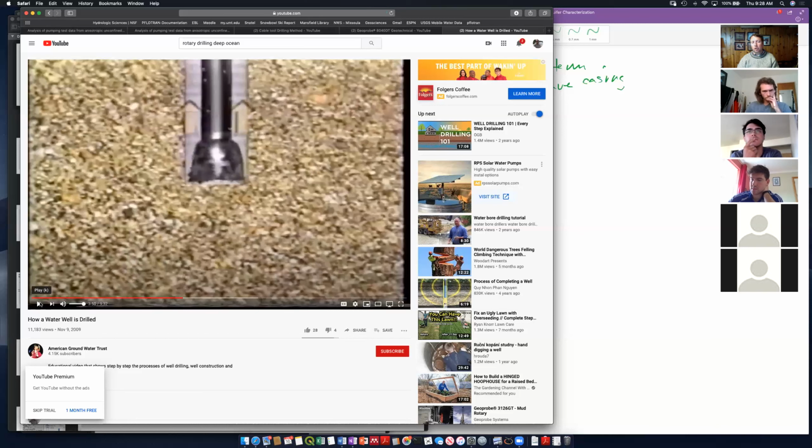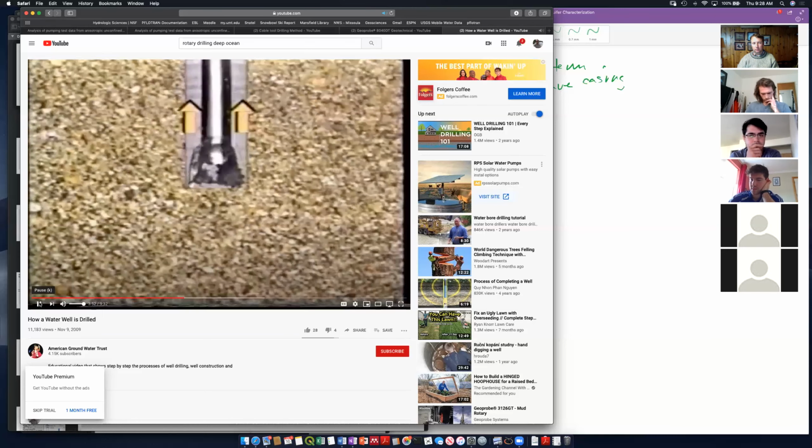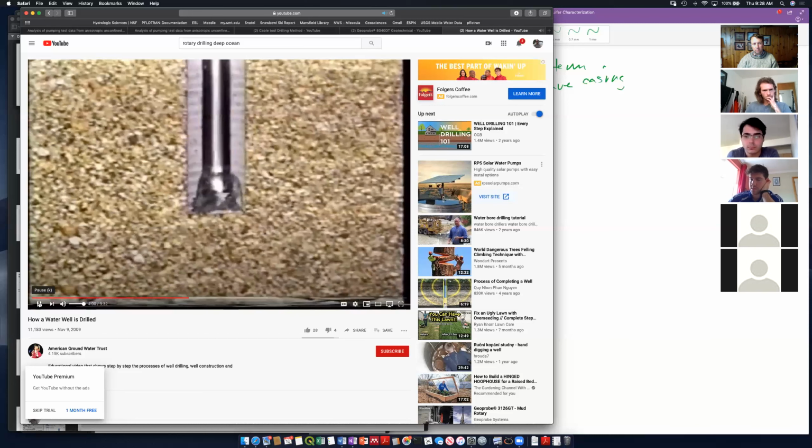Okay, so drilling mud is just one. I would say probably most water wells are drilled anymore with air, but you can use air, water, or mud. This drilling fluid also serves to cool and lubricate the drill bit, and by stabilizing the wall of the hole, it can prevent possible cave-in before the casing is fitted into the hole.